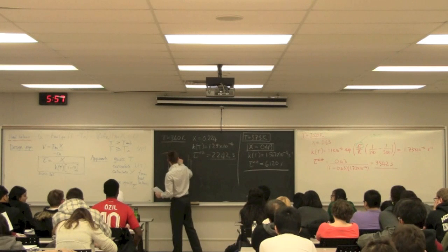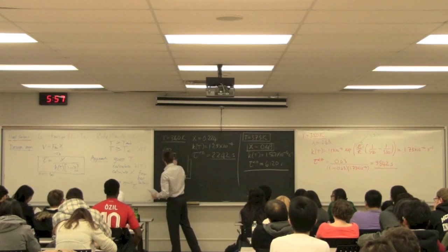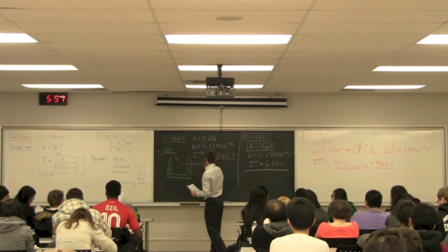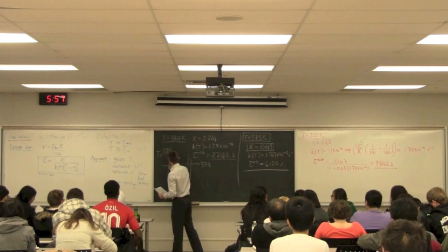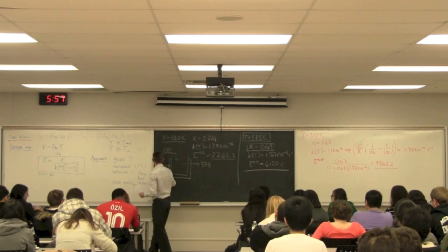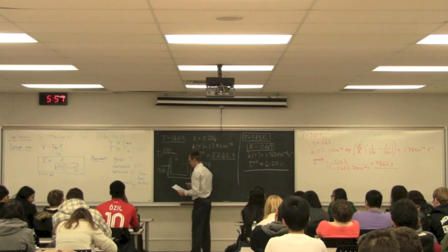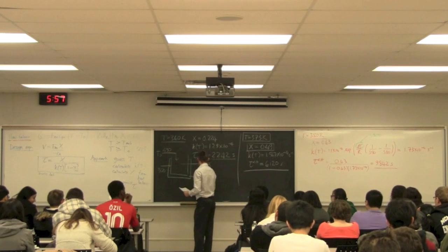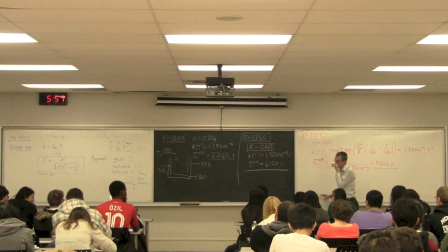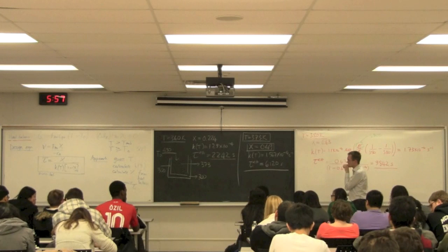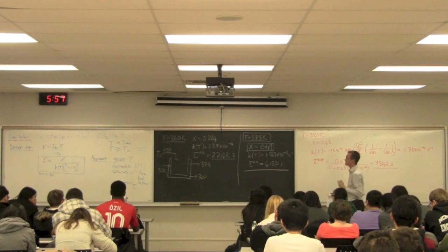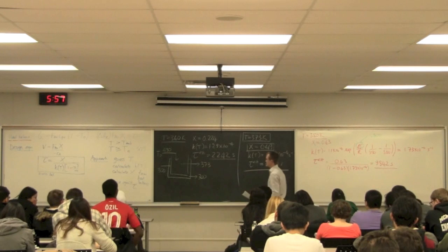So we've got T naught coming in at 450. We've now established that the temperature leaving over here is 373. My ambient temperature entering my jacket is at 300. Q is the amount of heat being transferred from the jacket to the reactor. So is Q negative or is Q positive? Negative. So Q's sign is that it's the heat added to the system.